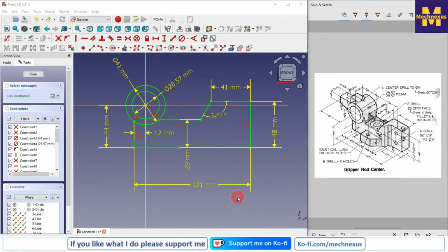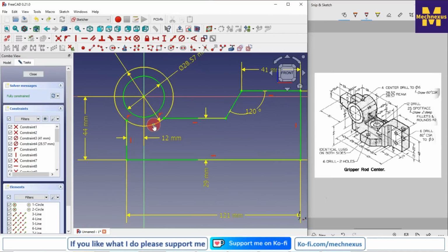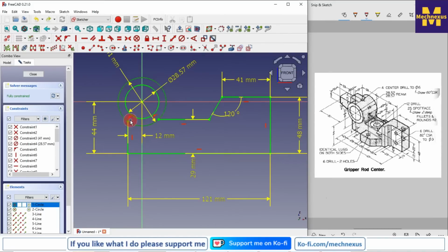We have a fully constrained sketch, but here we can see that we have two boundaries, so it will create a problem in extrusion. We have one boundary here and we have one boundary here, so that will create an issue in extrusion. So for this we can trim it, or we can make it a construction and create a 3-point arc. So the better way would be to trim it. So I will use the trim tool and trim it.